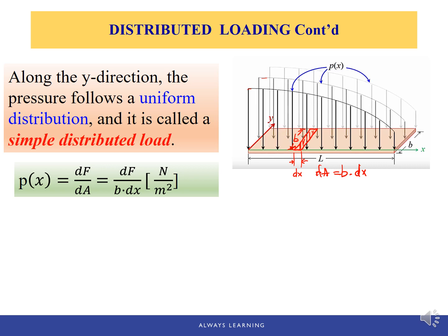Now, based on the definition of pressure, pressure equals F over A, and since force is a variable, we're going to use the differential form, which will be dF over dA, and we can replace dA by b times dx.